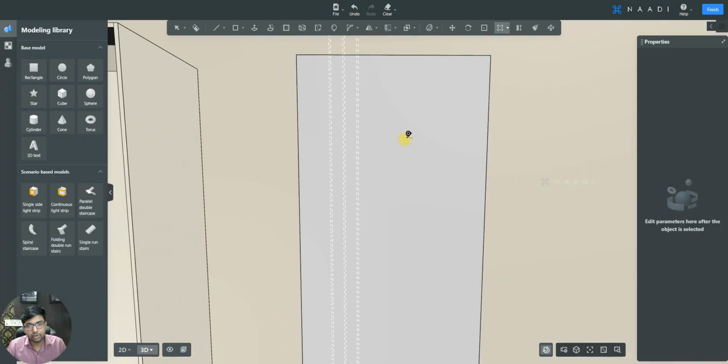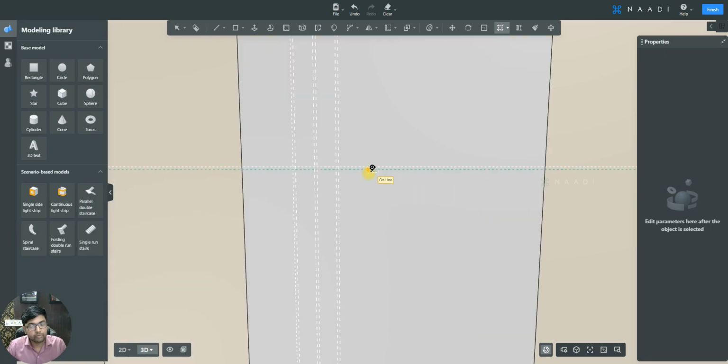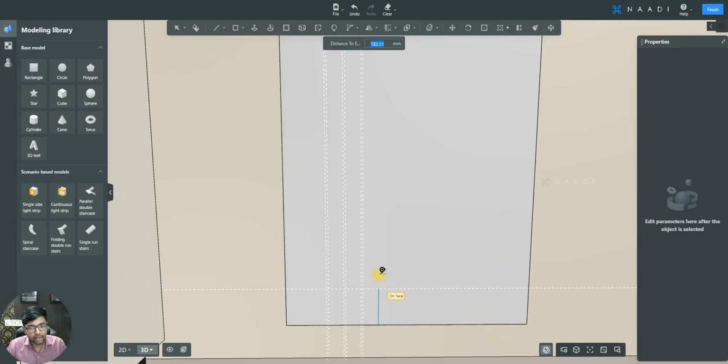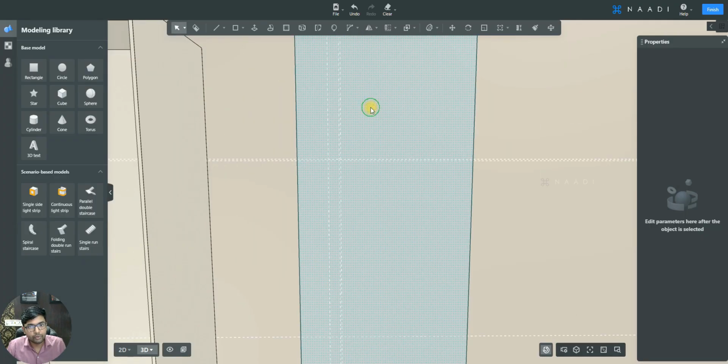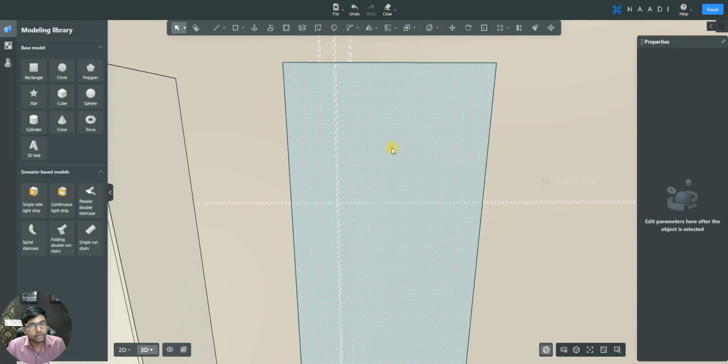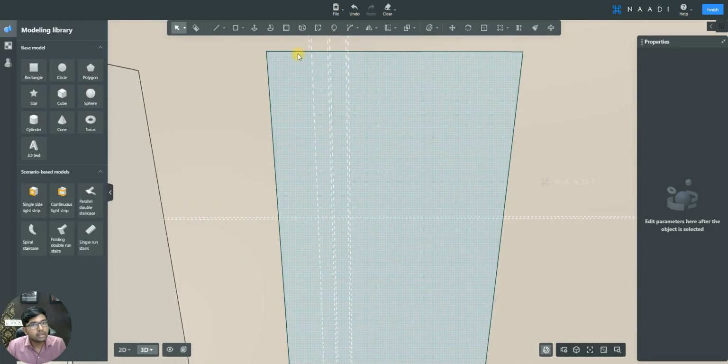And this horizontal groove should be placed at a distance of 800 mm from the top, and its groove should be 10 mm wide. From this point, the finger groove handle should start and it should end at a distance of 250 mm from the bottom. So can you see here, we've used our reference line to first define the position for the groove points. And once that is done, then the process is simple.